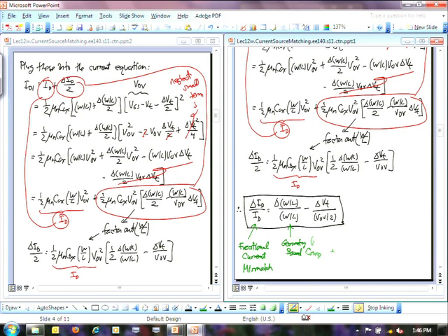And so we're going to talk about ideal op amps very quickly, sort of a review of what we've already gone through. Then we'll start talking about differential pairs, emitter-coupled pairs, something that I believe you've seen before. I see smiles, but I know you've seen that before. Offset voltages, maybe you've seen that, maybe not. Then we'll start talking about gain in op amps, finite gain. Two-stage op amps, let's talk about the design of op amps. There's single-stage, there's two-stage op amps. Some of them use cascode, some of them don't.